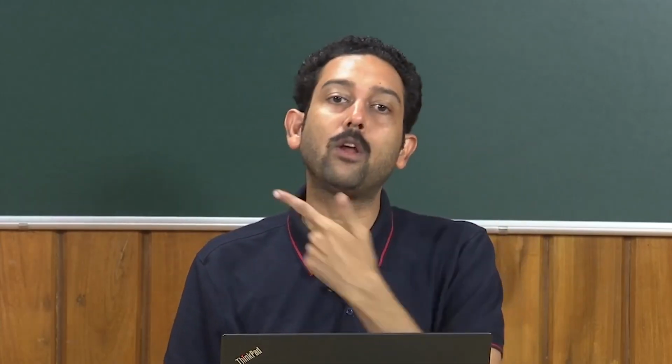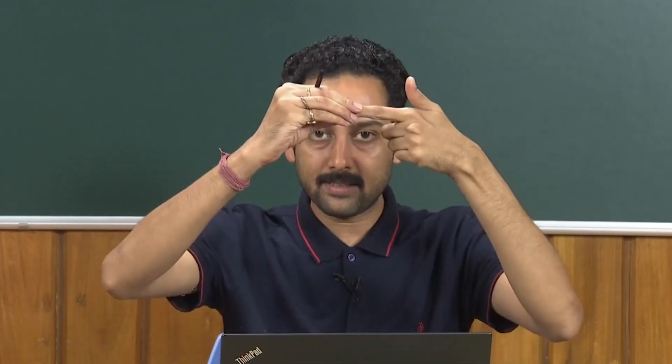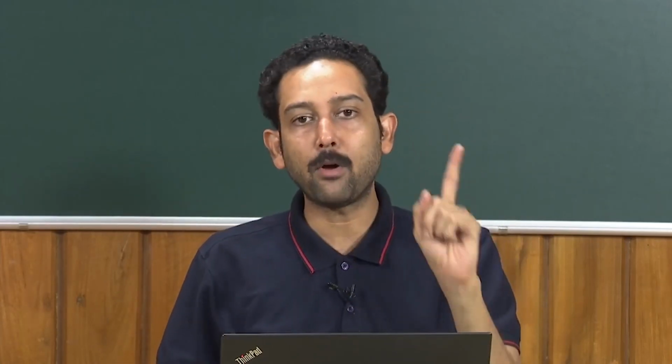Then there is something called a single stuck-at fault model, which was the most popular one. That is, at a time you assume that only one line is having a fault. First you test whether this line is stuck-at or not, then you go for another line and so forth. You assume that at a time only one line will be stuck-at or not.